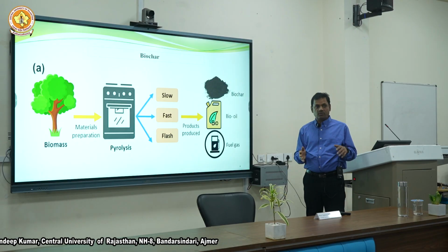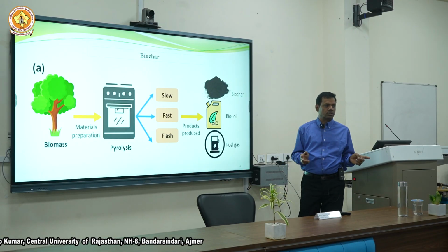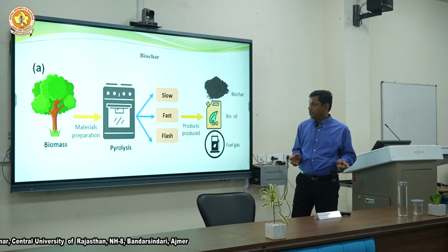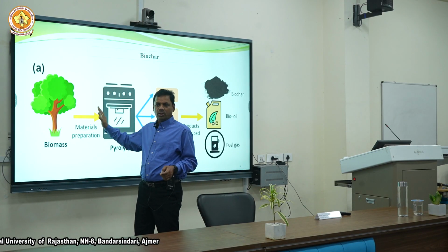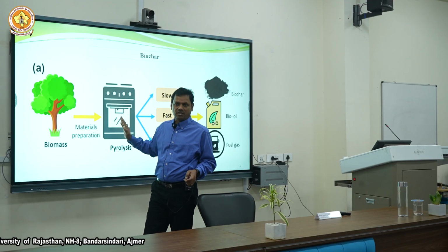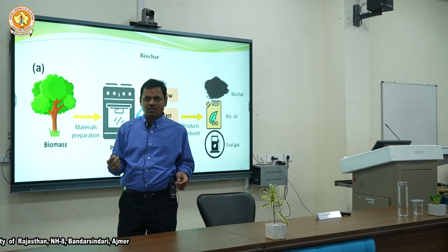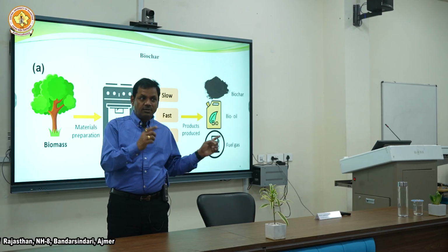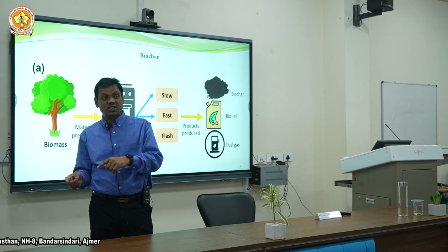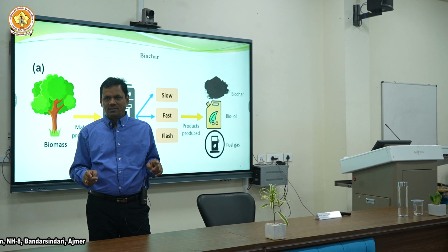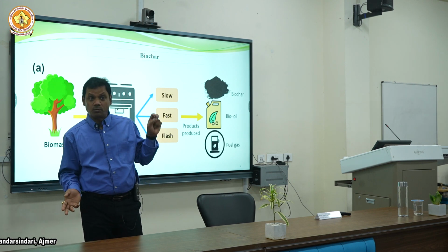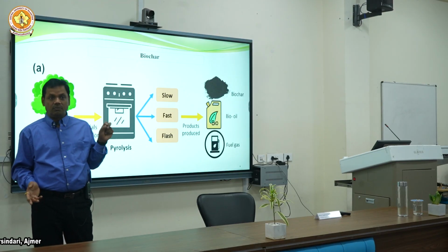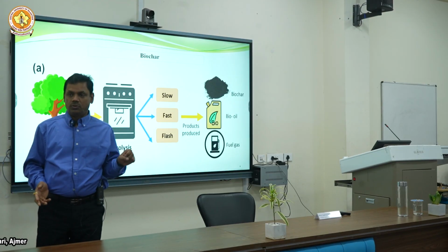This is the difference between hydrochar and biochar, how they are produced. If you have a waste material that is not dry, if you are doing pyrolysis, it's not efficient, because you are heating water. And if you have a dry material, if you are doing hydrochar, again that's not right. You are adding unnecessary water and then doing the process. So both processes have applications. Now we should use our judgment on which one to use.